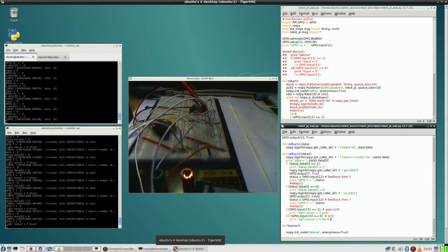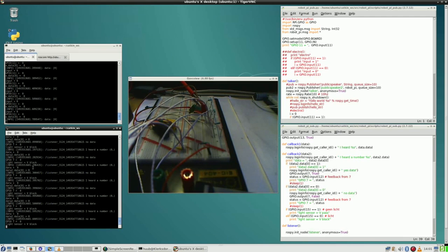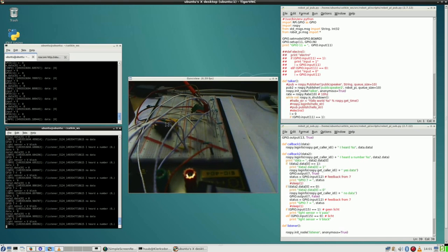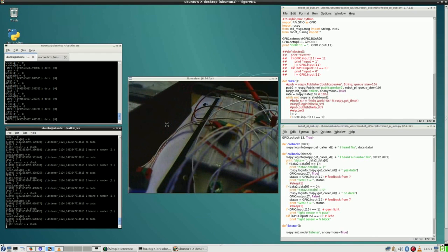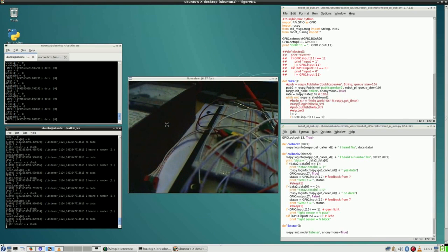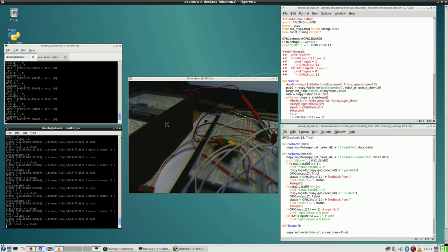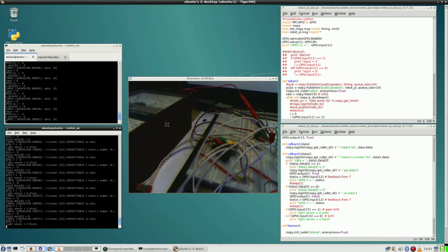Checking the circuit, it really doesn't make much sense. Right now you see in this terminal V block. V block says there's light. Well, this LED isn't burning, the lamp clearly isn't burning, and the needle of the multimeter is solidly at 0.